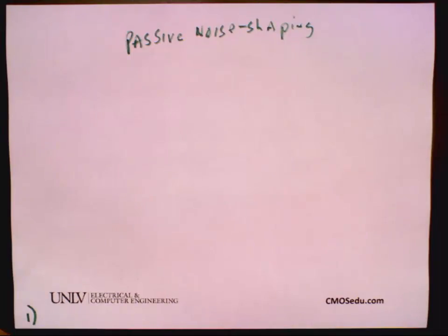Yeah, 4 bits. It should follow the theory, but you have to keep in mind two things. If you plot on a dB scale, you're not going to see much of a hump. It's going to be flat because 20 dB is 10 to 1, right? So if it's going up, it'll be hard to see. So you need to plot it on a linear scale. And then your peak noise, it's not going to be like the 1-bit where you get a lot more noise when you do the derivation.